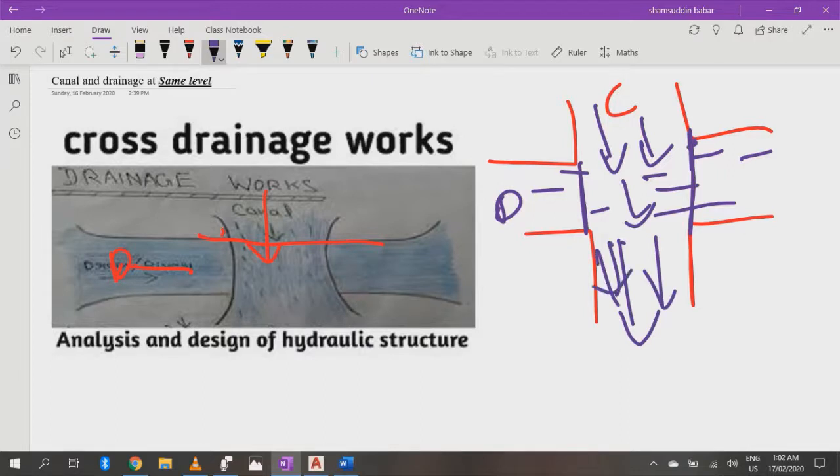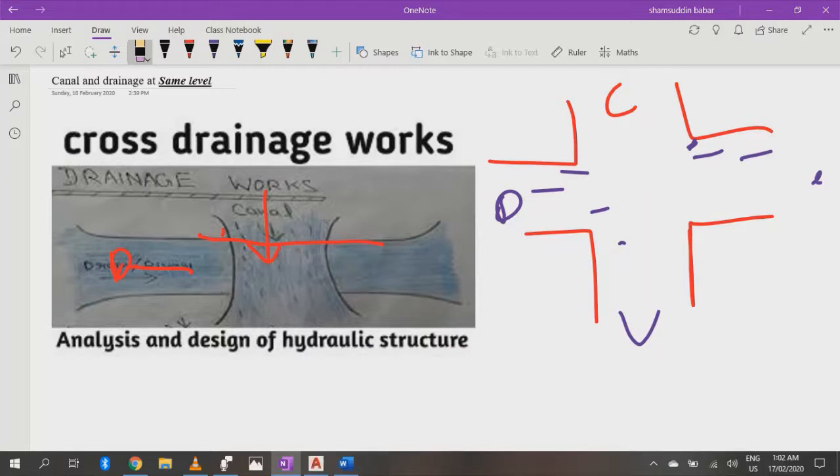Okay, that is when the canal drainage line is stopped. But when the drain is in flood, meaning the drain is flooded and it's flowing, the canal regulators are kept closed and the drain regulator is fully open.